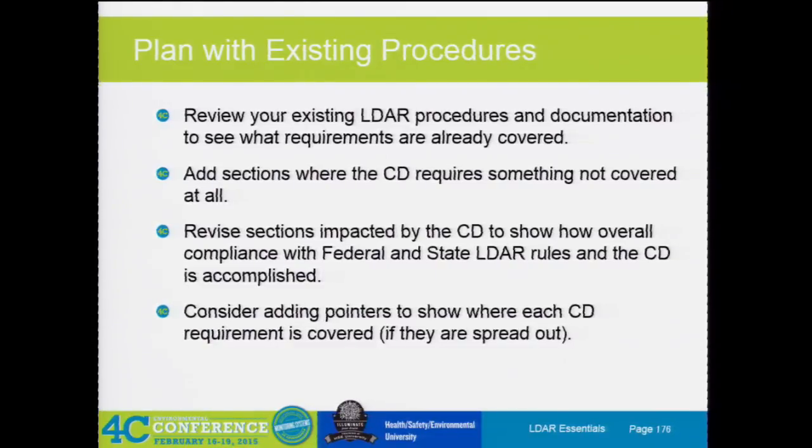So with South Coast Rule 1173, most folks just say this is my most stringent and this is what I'm going to comply with because the leak definition is lower and my repair time frame is more tight, et cetera. But when you do that, you also want to make sure that you don't miss some nuances. So for example, with 1173, pumps have to be repaired by day 6. They don't get 15 days, they get 6 days to do it.